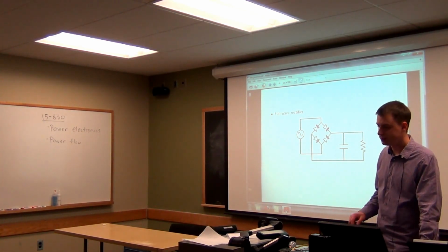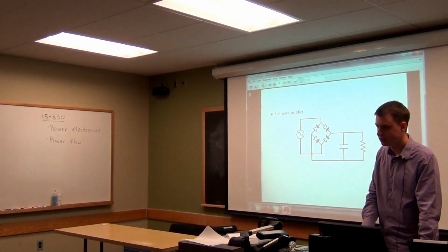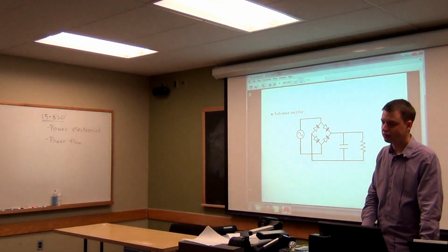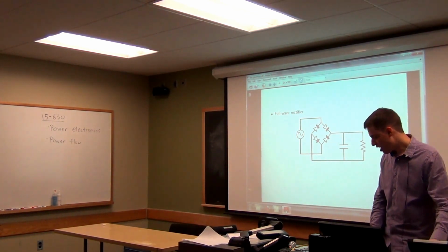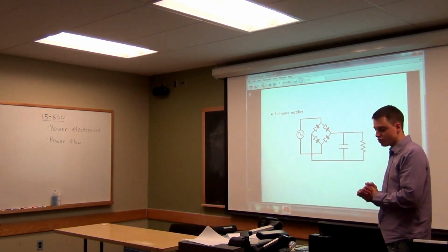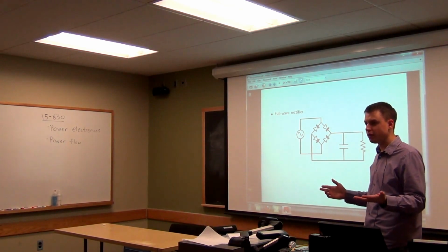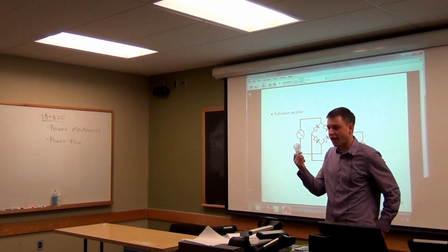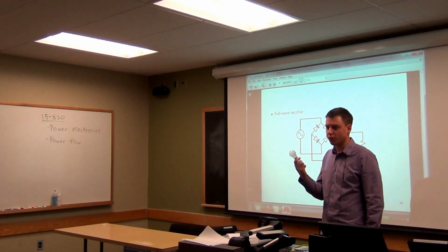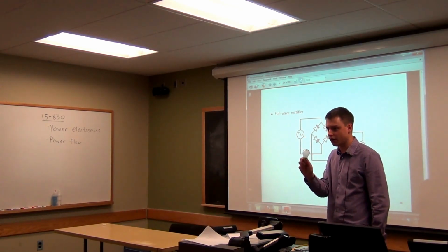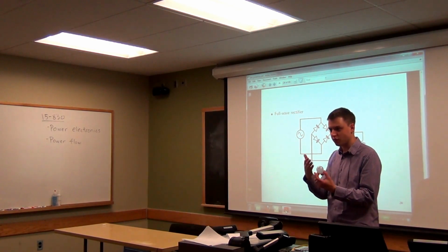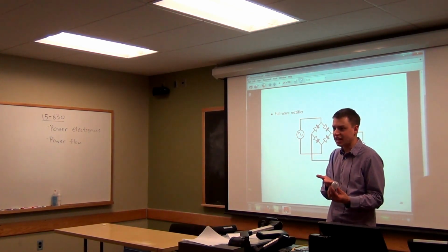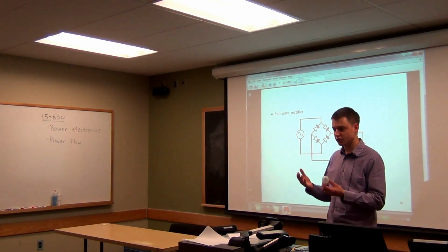Doesn't the electric dryer need constant voltage too? Because you said it would look more sinusoidal. Yeah, the electric dryer, no. So electric dryers just have a big resistor, right? So you can think of that like a light bulb. You can put AC current through a light bulb and you don't notice anything different about it because the heat is actually what builds up, and so even though the voltage is going back and forth, it's still generating heat both ways. Heat has enough mass to sort of keep going.